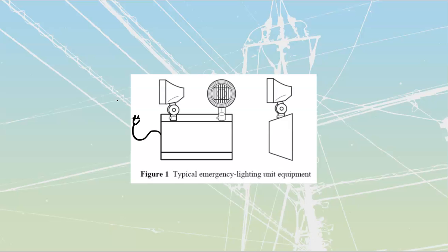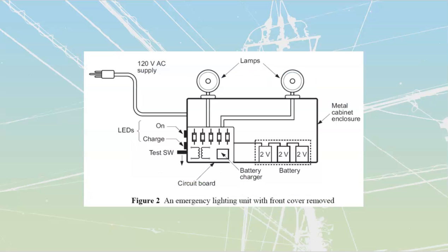For construction of these things, they're usually going to be LED at this point. They used to have a lot of incandescents utilized inside of these, but that has all disappeared at this point, because with incandescents about 90% of their energy gets converted to useless heat, and only about 10% ever makes it out as actual light. So we do not see these things widely used anymore. Old installations will still have them, but new installations are mostly going to be LED.